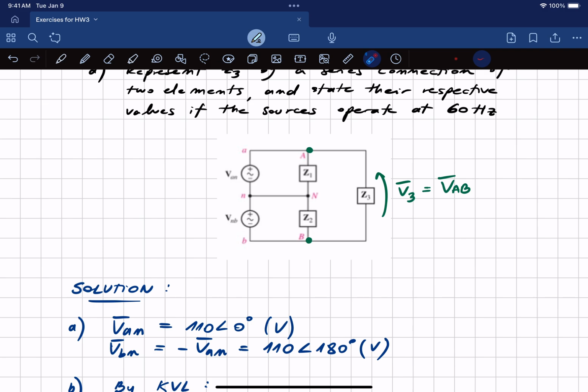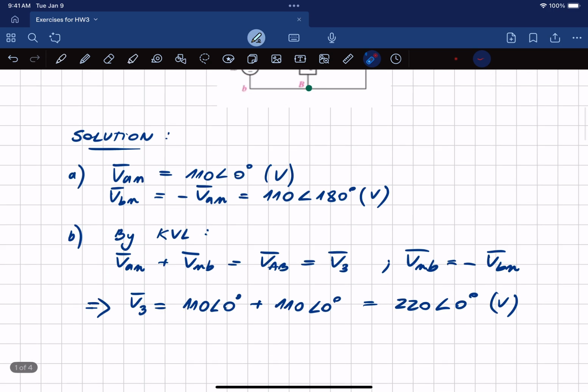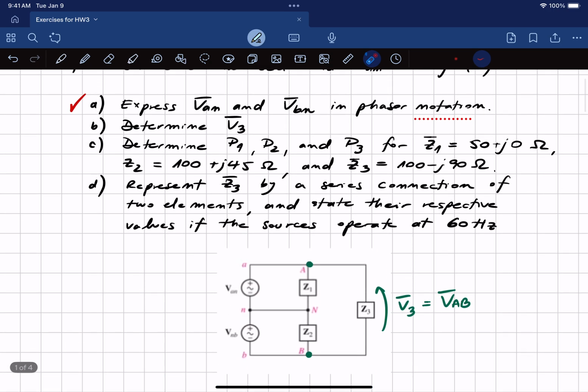You have outlets that are the most common ones that run on 110, but you also have a phase-to-phase connection, which in this case corresponds to 220 volts. And the elements that consume more power are usually connected to those two terminals, just like a washing machine or a dryer. Okay, let's move on to the next one.